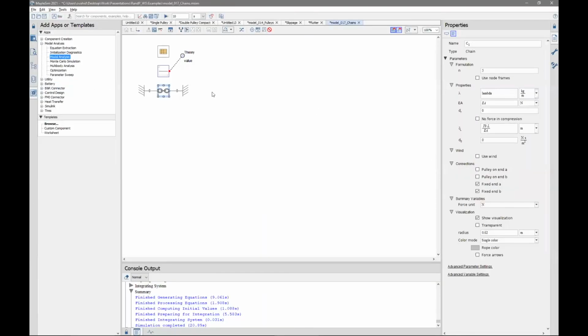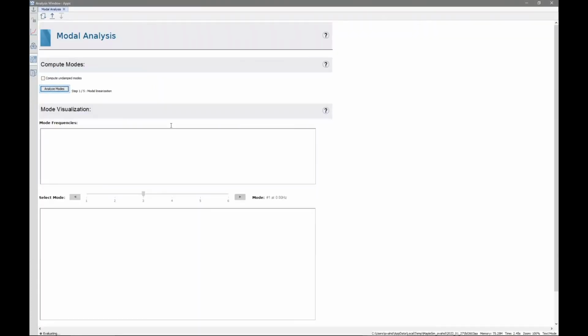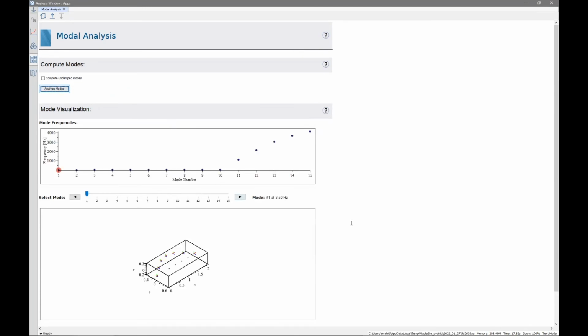Quick look at how many points we had. So we only have 5 middle nodes selected. The more we have, the closer we expect to be to theory, but this process will also take longer because we're dealing with more and more equations. So there are 5 steps to go through. Linearization would be the most important and the first one, and then analysis. And here we can see that the first mode of the vibration is actually 3.5 Hertz.